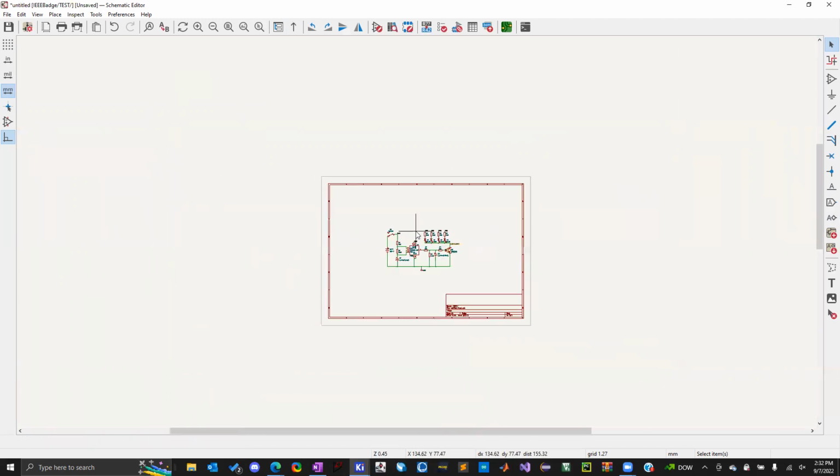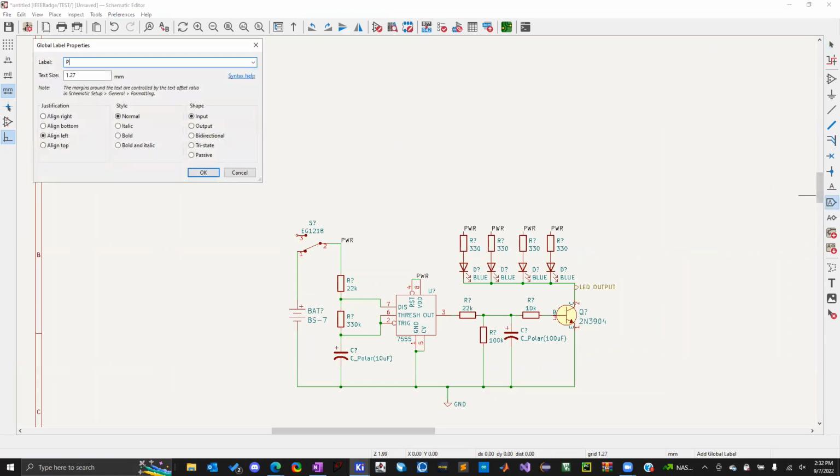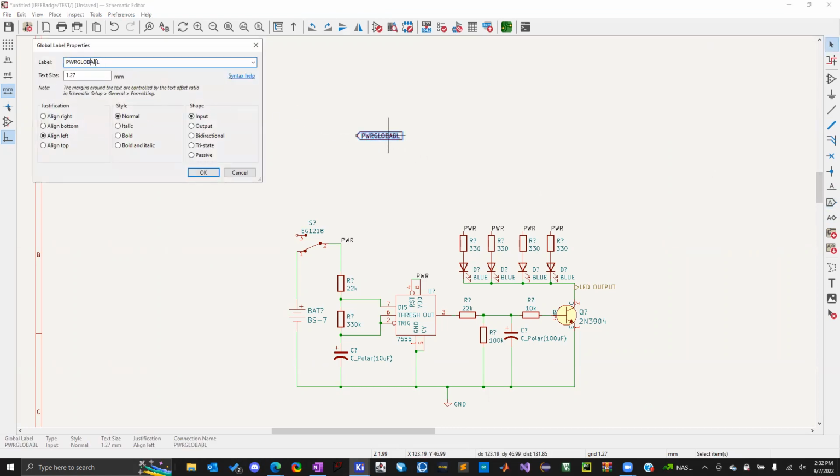An important thing to keep in mind, last thing with the nets here, is that all these powers are only connected within this hierarchy sheet. So if you have a power net anywhere outside of the sheet, it will not connect unless you're using this net label here. This is a global net, and I typed global wrong.